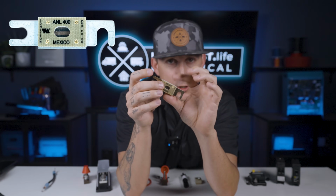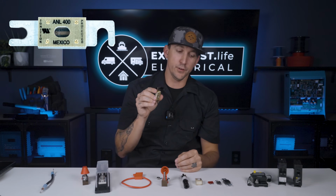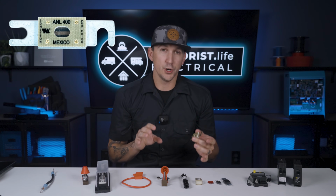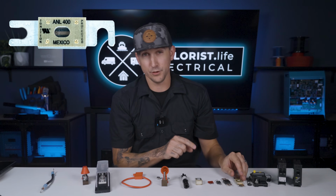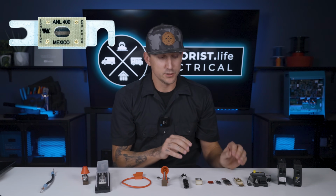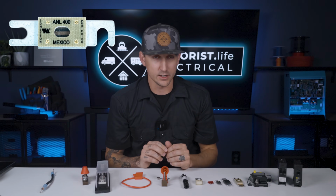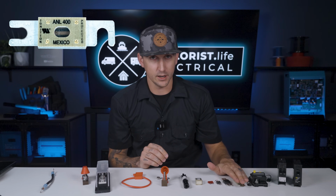and it's going to stop the flow of power. Now, there's no way to reset this like there is a breaker, but this particular fuse is going to be used in a location where there's no way for it to be overloaded accidentally. That fuse needs to be sized so that it can work under all normal operating conditions, and is really only going to blow if you have a short circuit event.